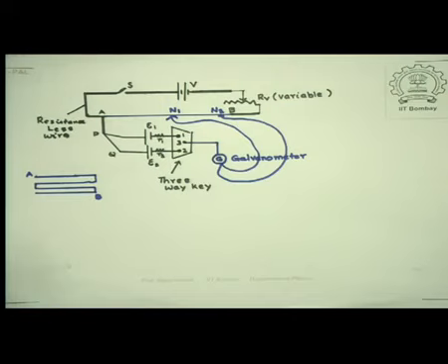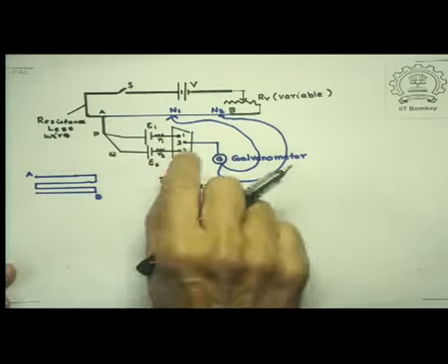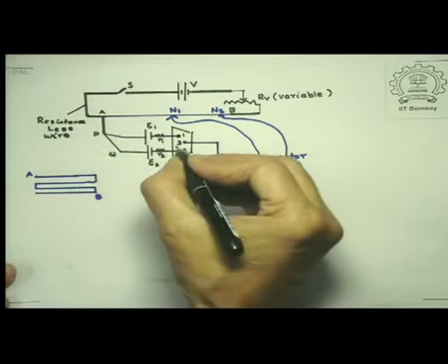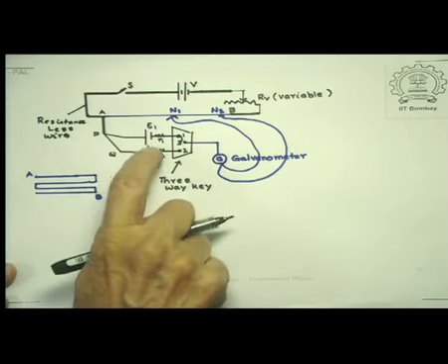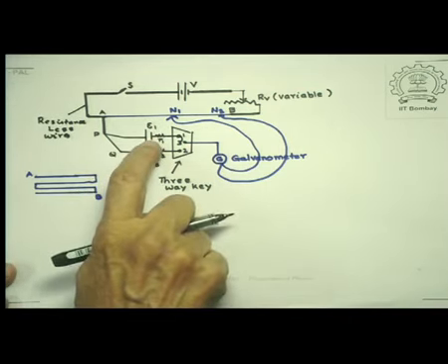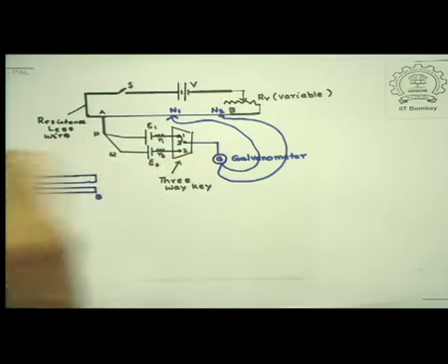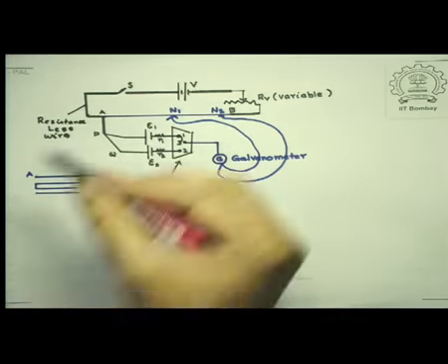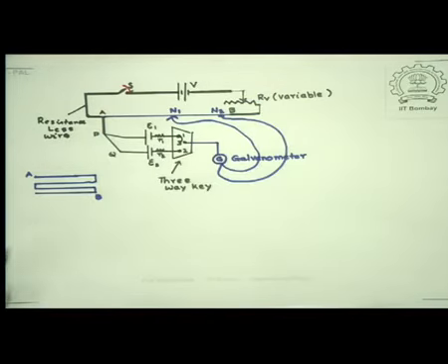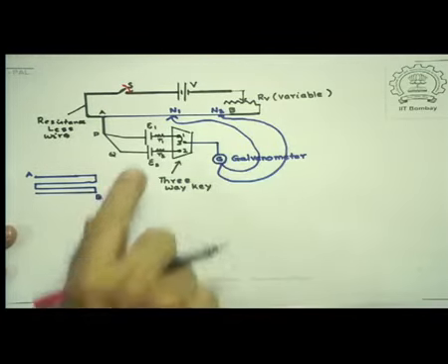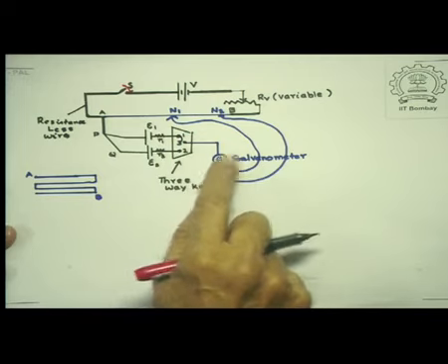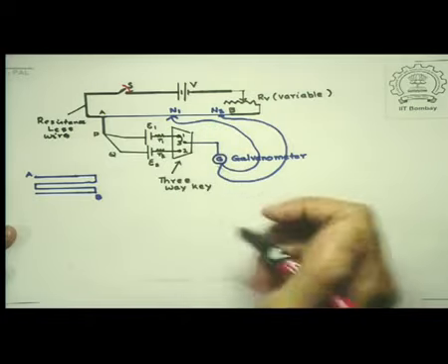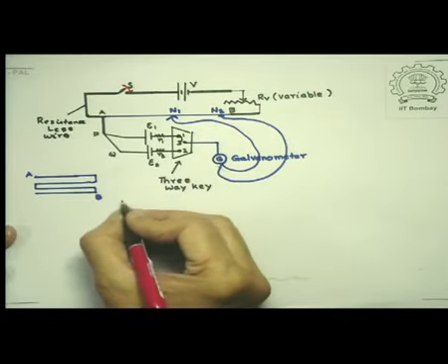The basic principle is the following, that let us say we connect 1 to 3, meaning thereby that the EMF source E1 is in the circuit but E2 is not. This switch S is kept closed. Now what we do is this, we slide this wire which is connected to the other end of the galvanometer such that a null deflection is obtained. So when the null deflection is obtained,